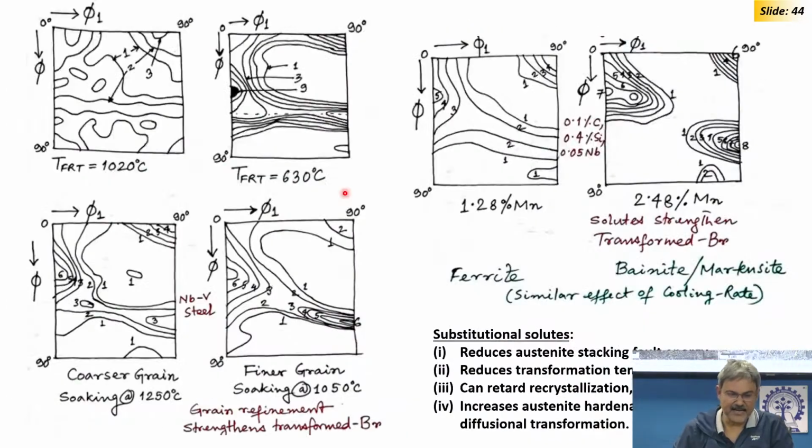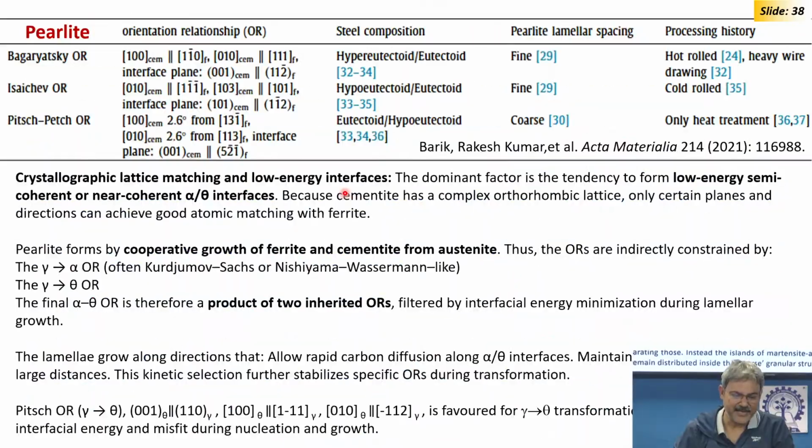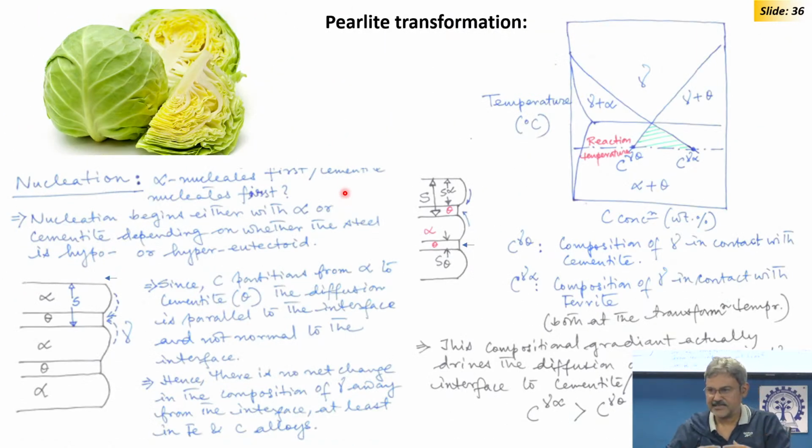Pearlite, what is pearlite? Pearlite is basically a cabbage, a pearlite nodule. A single nodule is a single crystal of cementite forming like a cabbage, and if you dip the cabbage in water, that water is your ferrite matrix. So, that is pearlite. If you cut a section, you will see only some leaves like this. So, we call that a colony, some leaves like this, some leaf like this. As you see the section, leaves are oriented in different ways. So, what is important is the interlamellar spacing and the cabbage size.